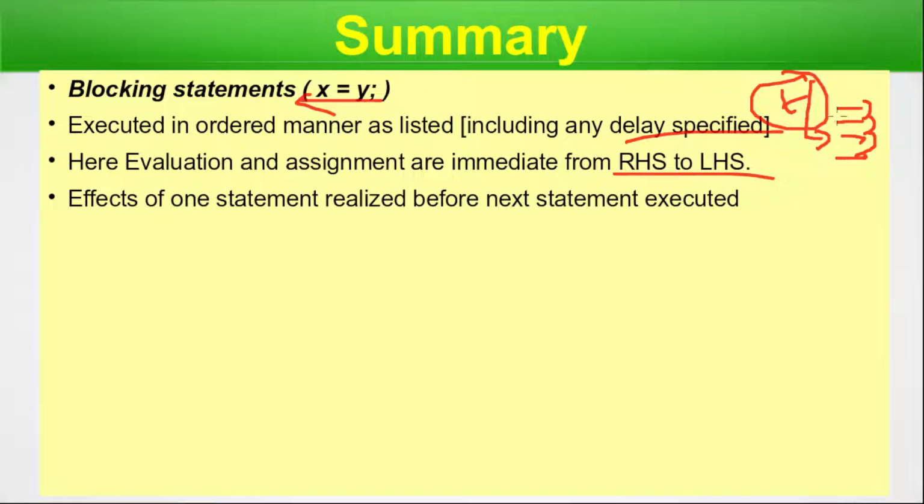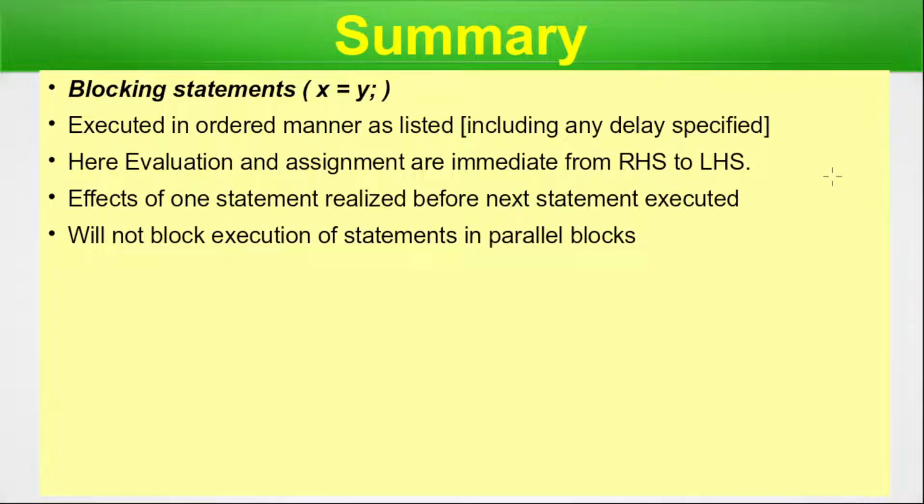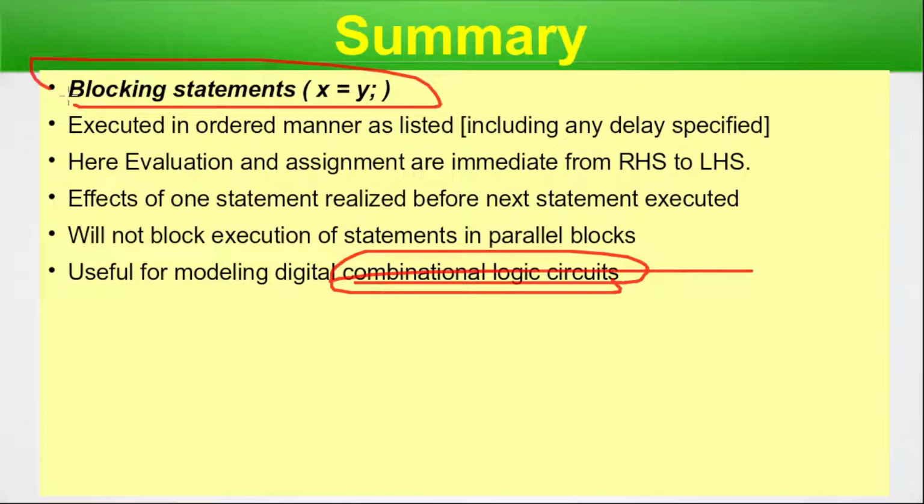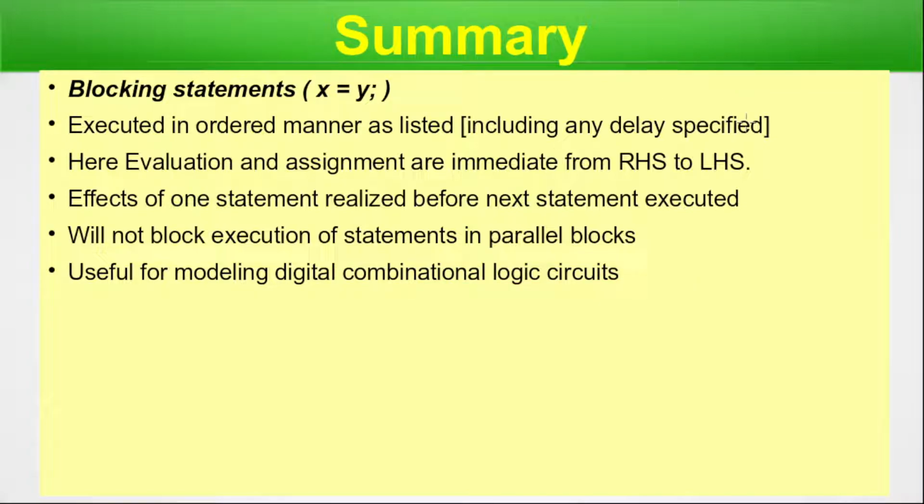So time will not change. However, inside the time, all these equations will execute sequentially. They will not block execution of the statements in parallel blocks. Parallel blocks will happen in a parallel fashion, like multiple always blocks or multiple initial blocks. Useful for modeling digital combinational circuits. For combinational circuits, we use the blocking assignments, also called the blocking statements.